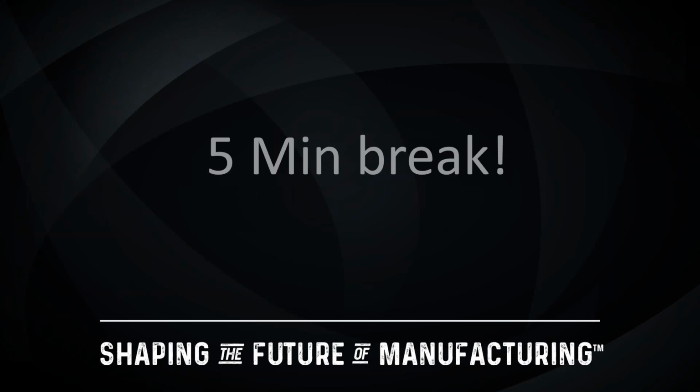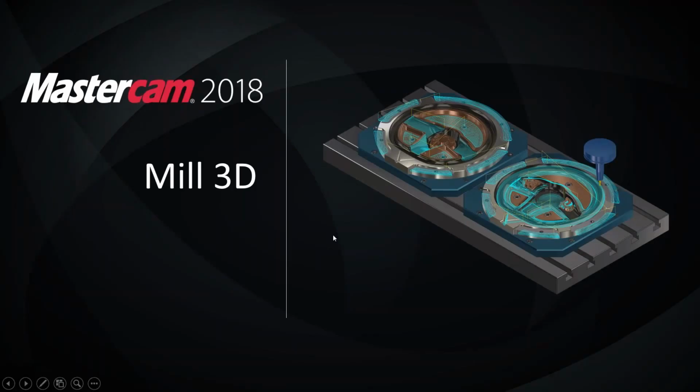Spring pass, same thing as what I call a pressure pass. It just runs the tool the same at the end again. And Josh, yeah, that's correct. A spring pass is basically going to run an identical motion to whatever the finish pass was for that toolpath. So, accounting for maybe any tool deflection or just cleaning up to make sure that the part is size on size, you can run however many springs you define in there. So, yeah, there might be some different nomenclature on how people name that particular feature, but it's doing an exact copy of whatever your finish pass is.